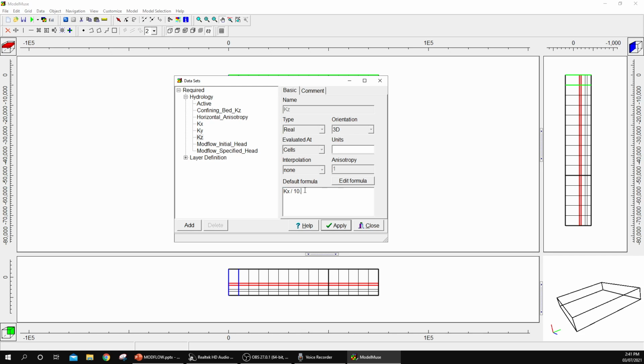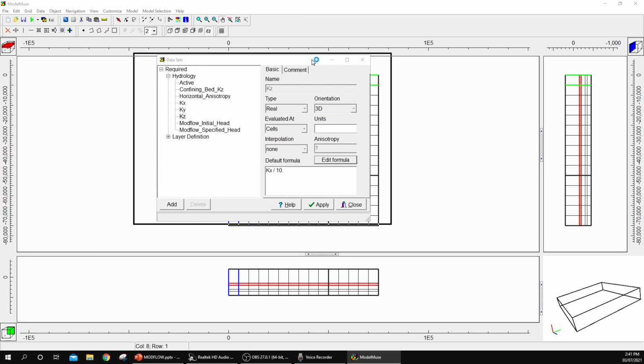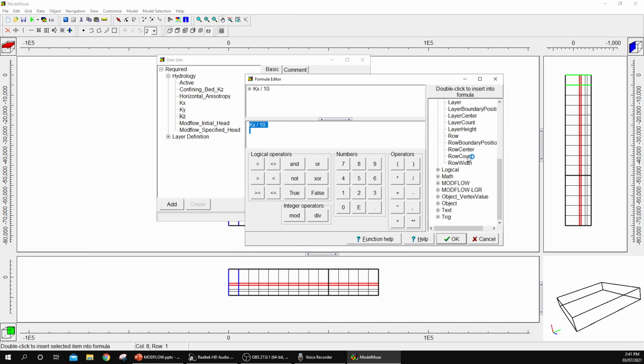It's easier to obtain the lateral hydraulic conductivities, K sub y or K sub x, and sometimes we approximate the K sub z as K sub y or K sub x divided by 10. Of course, the best way to estimate the K sub z is to consult literature or textbooks like Willis and Kresic, and look for the relationships between K sub z and your K sub x. So for now, for this example, we'll just edit this value.